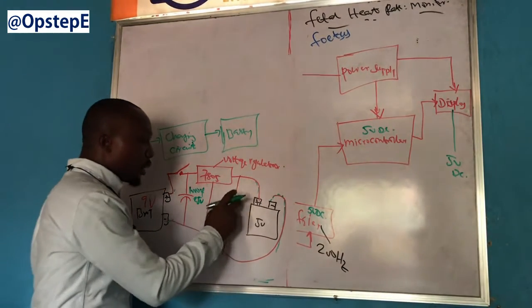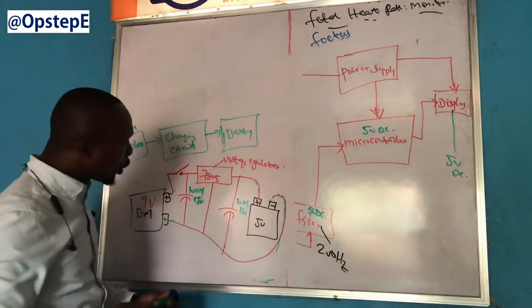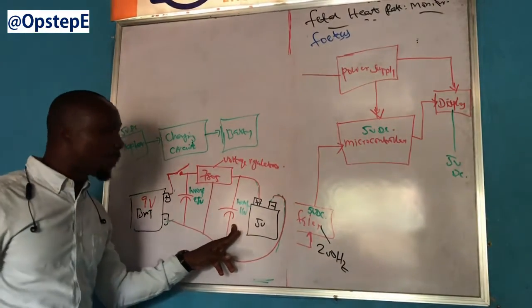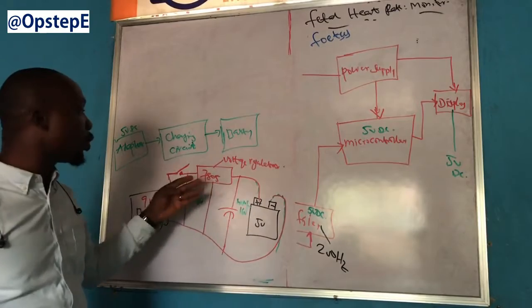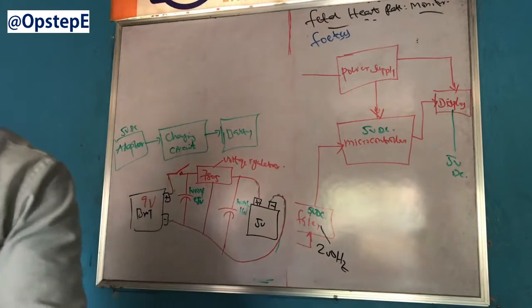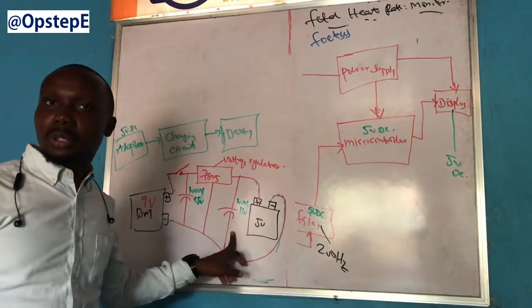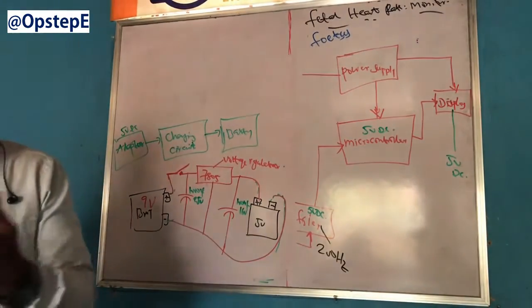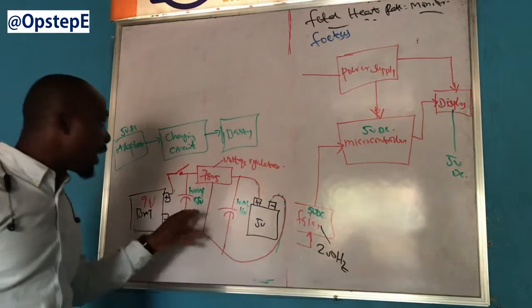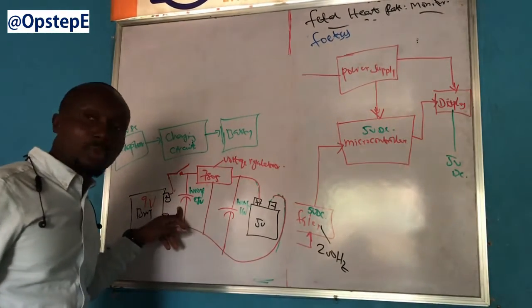The value you are going to use here will be 100 microfarad, 16 volts. The question again is, why do I need a capacitor at the output? The reason you need a capacitor at the output also is because the voltage in question has gone through some transformation. A 9 volt voltage has gone through some transformation such that now you are getting 5 volts. Wherever ripple or spike has resulted in that transformation will be taken care of by this capacitor. That's why you have a capacitor at the input, and then you have a capacitor at the output.